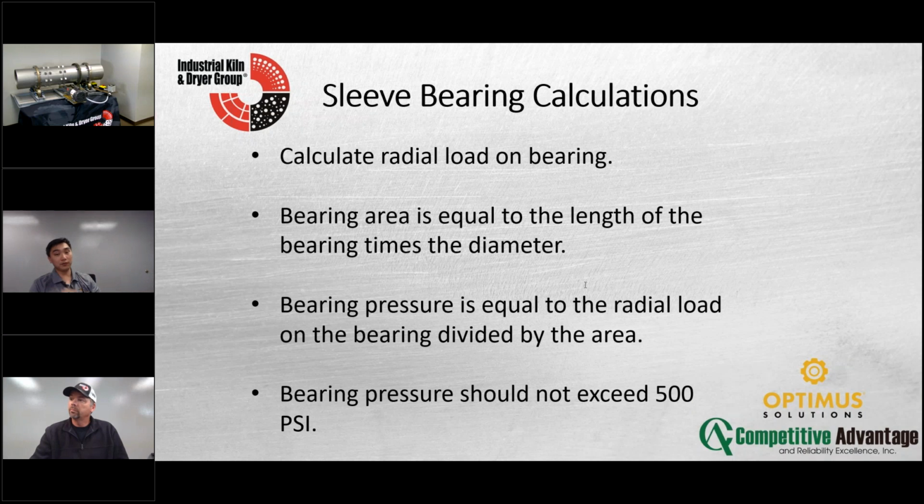I think you just did a drive replacement for a ball mill group in Ohio, and I did a vibration analysis on it. And we have a service that can help with it. We did a cross comparison with one unit versus the other. We can't give you a defined number because everything has its own unique specs. So we did a comparison of itself, or even say one bearing to another.